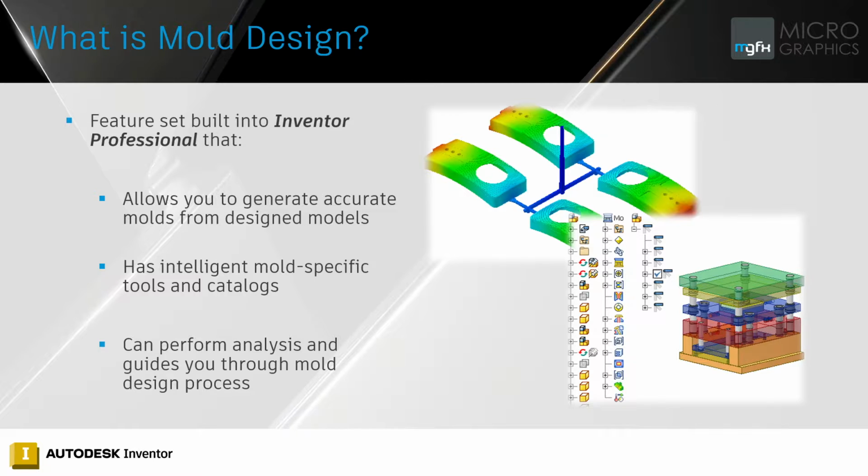You can also put in standard components and put in vents and cooling channels and what have you. Anything that's necessary for the mold design process, you can pretty much do it in the mold design environment. And lastly, of course, you can perform an analysis, and all the tools in every single ribbon will guide you through the design process.